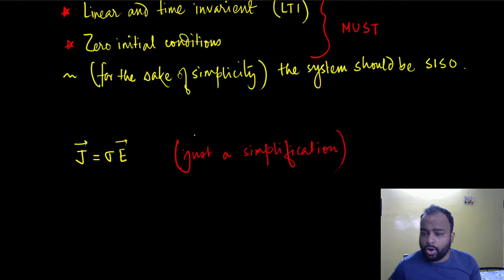There are so many non-ohmic conductors, right? Any conductor that conducts through vacuum discharge or things like that, maybe a fluorescent lamp, that's a non-ohmic conductor. Any semiconductor device is a non-ohmic conductor. Ohm's law does not apply. So really, in life, nothing is linear, right? And as such, we cannot really assume linearity everywhere.